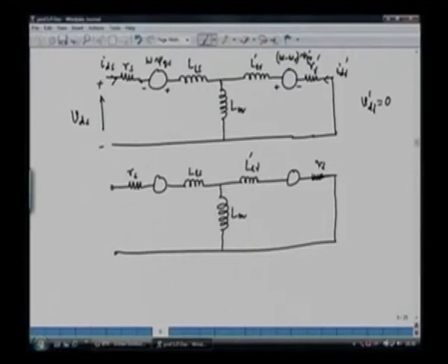and we have the same RR here, and the sign of the rotational induced EMF will be different here, that is omega into psi ds, and here we have VQS, the Q axis applied voltage, and this is IQS, the Q axis current, and this current is IQR, the rotor current in the Q axis, and again VQR is equal to 0, and hence the rotor is short circuited.